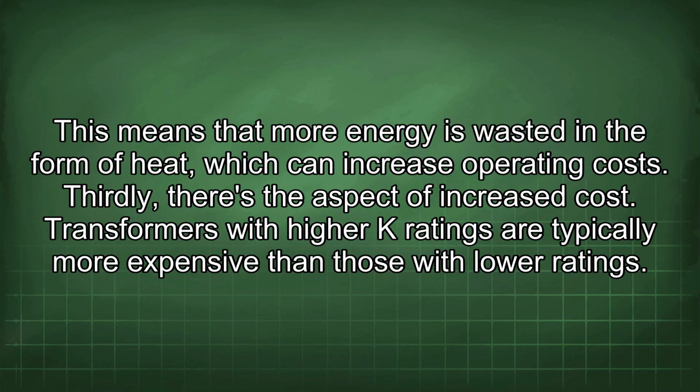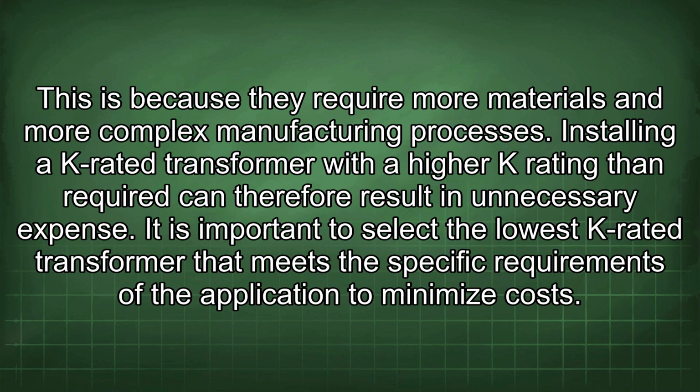Thirdly, there's the aspect of increased cost. Transformers with high K ratings are typically more expensive than those with lower ratings. This is because they require more materials and more complex manufacturing processes. Installing a K-rated transformer with a higher K rating than required can therefore result in unnecessary expense. It is important to select the lowest K-rated transformer that meets the specific requirements of the application to minimize costs.